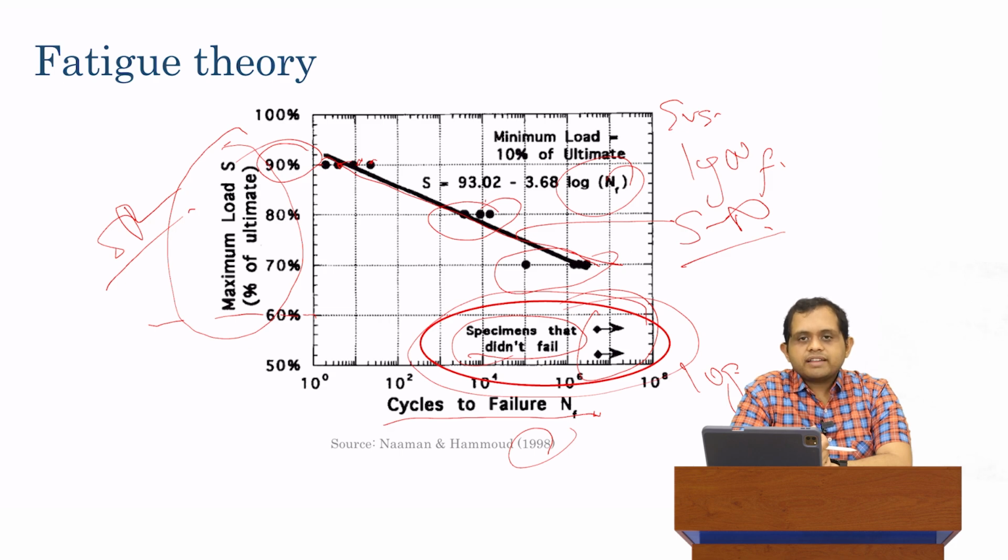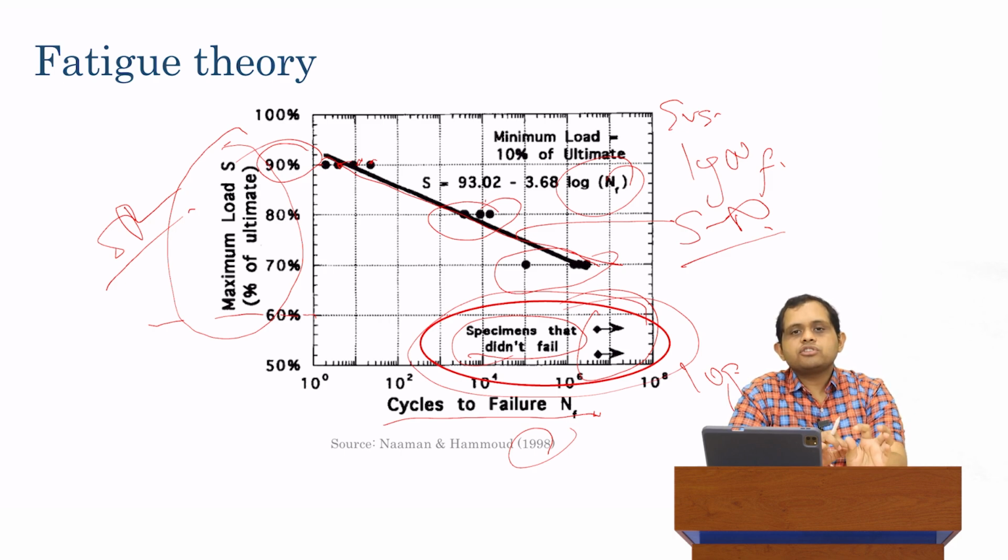In the static testing which we know for flexure, the material will fail at some point. We will always be able to get a flexure strength out of it. But it is seen in some tests, it's not seen in other tests, it really depends on the testing method, that if you put the stress ratio low enough, a macro crack actually never develops, or the modulus never actually falls below 50%. It kind of just reaches a flat value and then nothing ever changes.